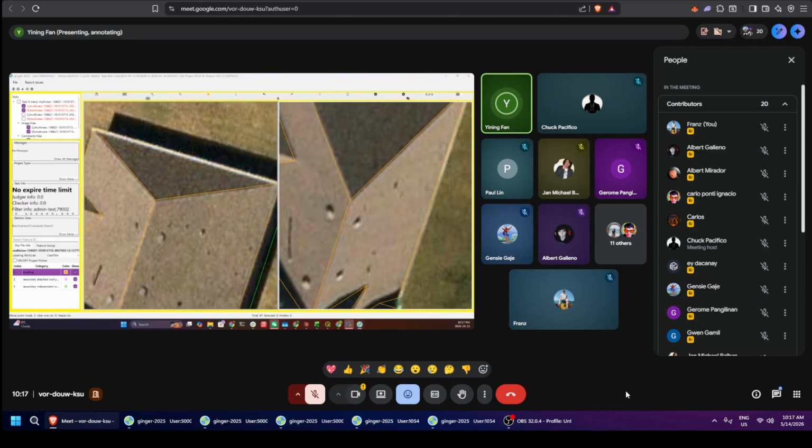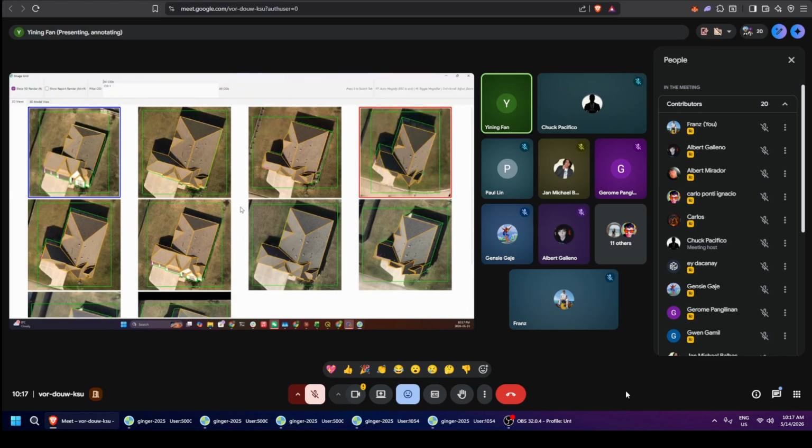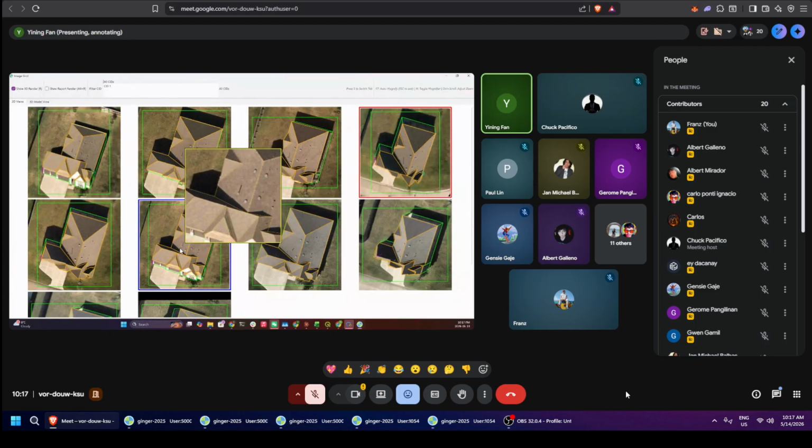Also press F7, you will enter the imagery selection grid, just like other 3D products. But in this one it's a little bit different. You can see that once you hover over the individual frames, the photo is automatically magnified, so you can check whether the ridge and everything is matching with the underlying image. You can also turn it on and off by pressing R on this interface, and by pressing Control and scrolling, it will keep magnifying, and you can see all the details down here.